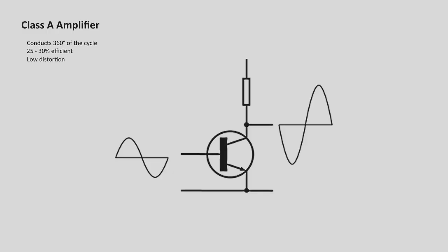Class A power amplifier designs have been largely replaced by more efficient designs. Their simplicity, though, makes them popular with hobbyists. There is a market for expensive high-fidelity Class A amplifiers that are considered cult items among audiophiles, mainly for the absence of crossover distortion and reduced odd harmonics and high-order harmonic distortion.